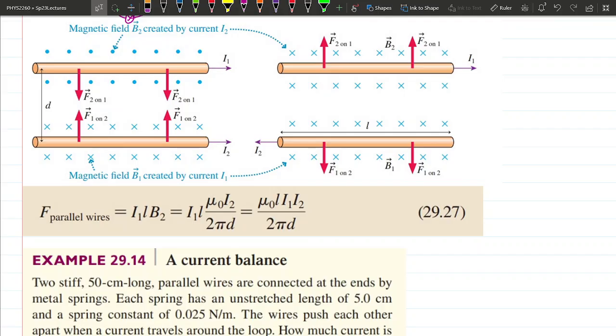So if you imagine a cable, like a power cable from your laptop, there's actually two wires, right there. This flat part: one is carrying current going this way, the other one is carrying current going this way. If you run enough current through this, they will actually explode away from each other. And this is a concern when you're carrying, not laptop current, but like if you're running a power station that's providing the power for the entire city of Turlock. You have to keep these wires kind of far apart so that they don't exert a magnetic force on each other and try to pull each other apart.